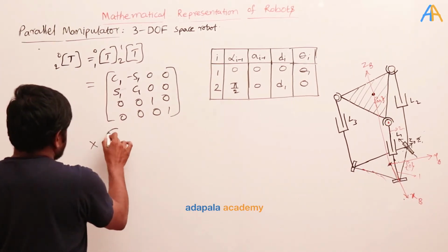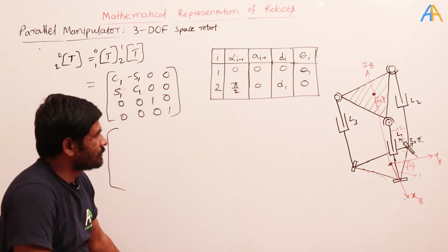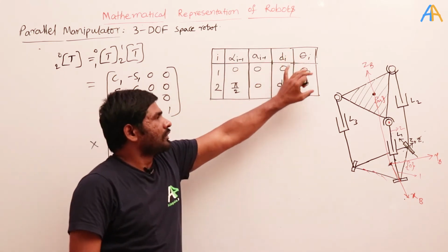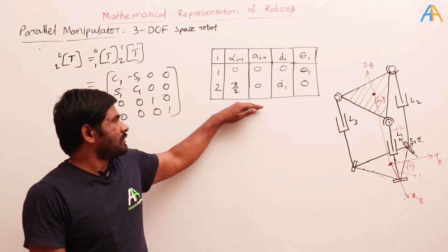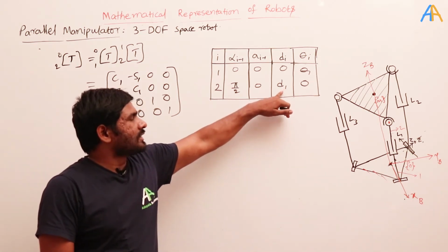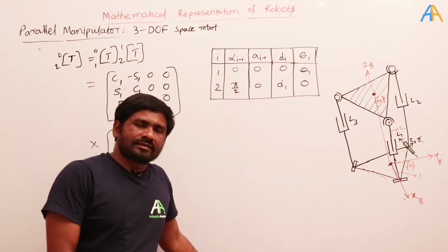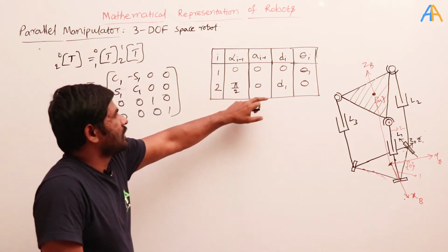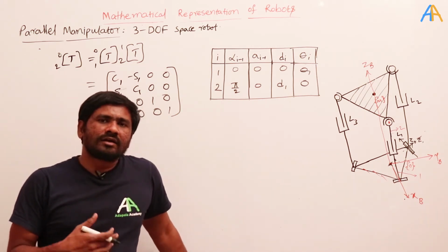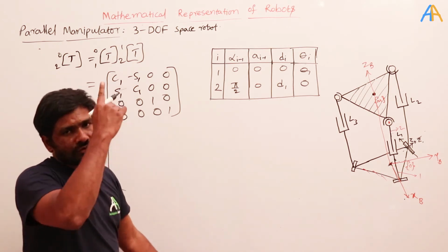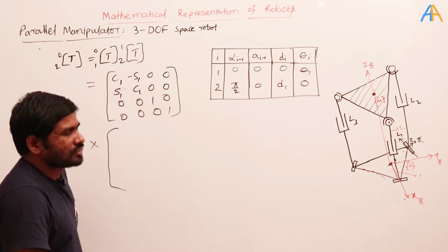Okay, into here, this is the second link. For the second link, if you observe, there is only one rotation and there is no rotation about the z-axis. So whenever there exists only one rotation, then I can directly add the translation along the z-axis into the variables related to the x. But if you have a rotation here as well as here, then I cannot write it directly. Then I need to write two transformation matrices and multiply them. Otherwise you directly substitute in the original matrix that we derived for the i minus 1 Ti.